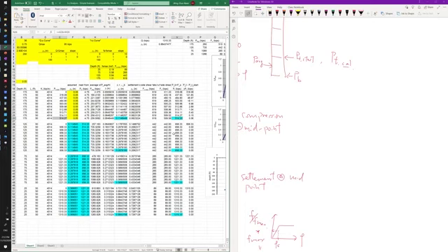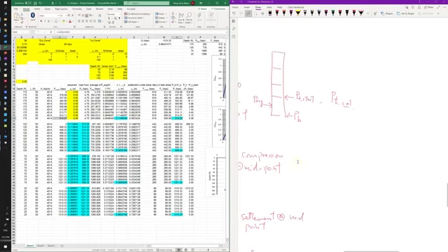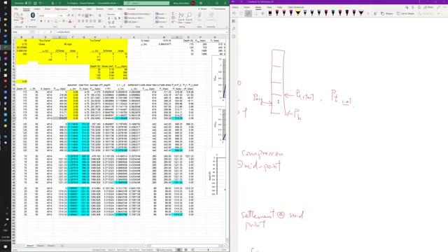So this is not the end of the day. Remember, for the pile you have 4 different elements for this one. You can divide into as many elements as you want. If you want accuracy, you can divide it into thousands, which I think is what computer codes do. Or at some point, elements n versus n plus 1 give you about the same answer.